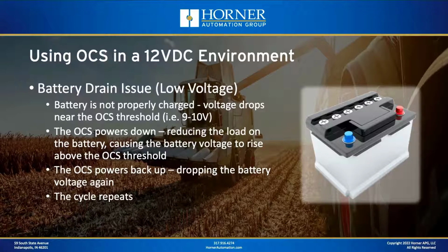Let's start with the battery drain issue. This is one we can all relate to. It's a low voltage condition. We've all left the lights on at some point and drained the batteries in our automobiles, haven't we? But the specific issue I'm talking about here is a scenario where somebody left the lights on, let's say, or some systems were left on, and the battery is not charging, the battery is discharging because of these loads. And let's say that the OCS is one of the devices that has been left on, and the battery is not charging, so the battery is slowly draining.